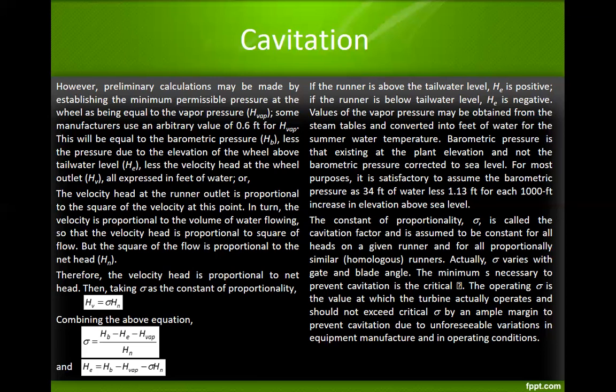Now, the constant of proportionality, sigma, is called the cavitation factor and is assumed to be constant for all heads in a given runner and for all proportionally similar runners. Actually, sigma varies with gate and blade angle.